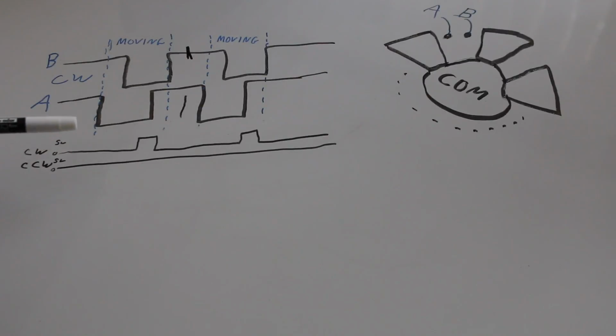That way I don't have to hack into the other signal, if we're going to call one a clock and one data, and then try to guess when data is valid with some other clever timing delays and stuff. This will just cleanly generate a guaranteed asserted signal when it has moved one way or the other.